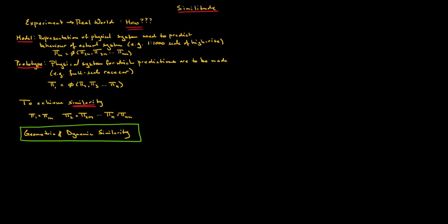So this is a variable that affects the pressure drop. Now what we want to do is achieve that same geometric similarity in the prototype. To match the model results to make prototype predictions, you would want that same L over D ratio.